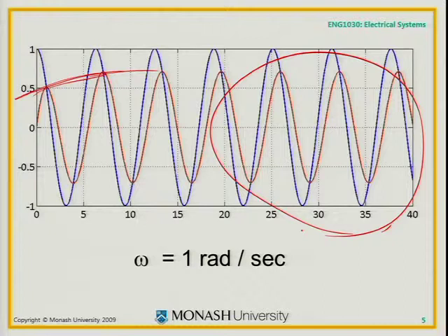But what is different is the amplitude. So the red one has a different amplitude, and it has a different phase than the input. And generally, that's what we'll have to keep track of. This has got a different amplitude than that, and it's phase shifted. The maximums aren't occurring at the same time. So steady-state sinusoidal analysis, which is what we're worried about, just involves determining amplitudes and phases all over the place. Amplitudes and phases. How have they been shifted around?